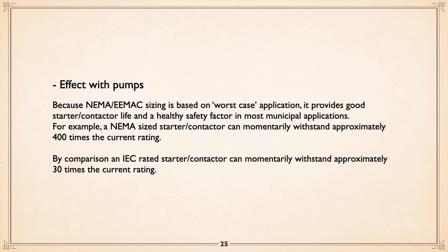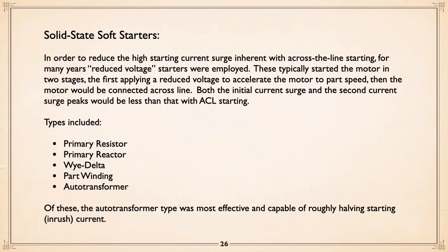People will, and even going to AC3, the rating, they still are smaller than what the NEMA units are. And they have a nasty habit, if they see high currents, of welding the contacts together, in which case when the overload says disconnect the contactor, it can't. So please don't use them.